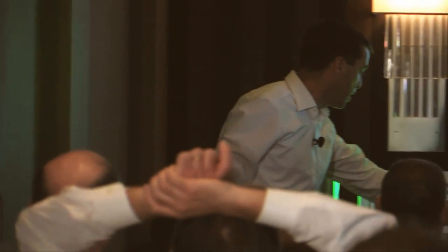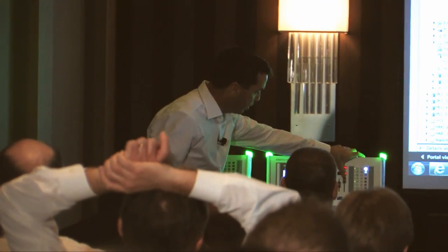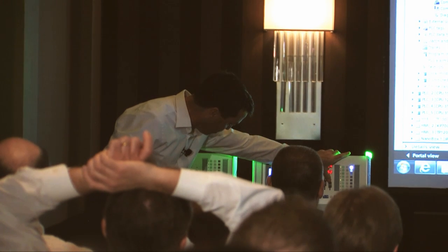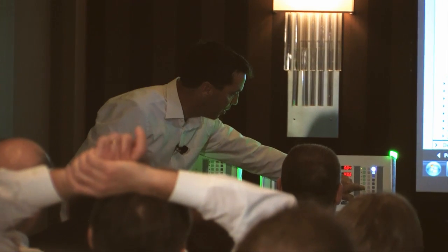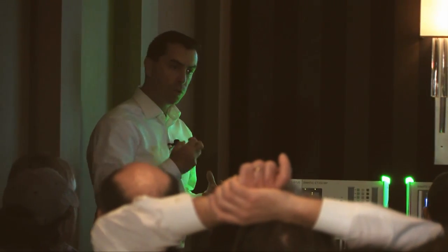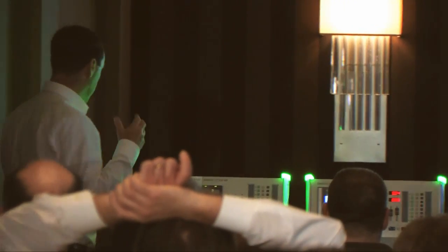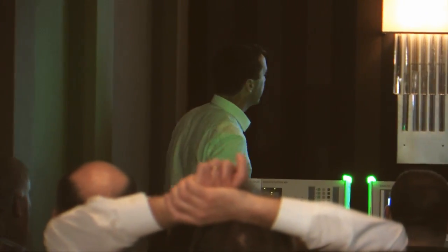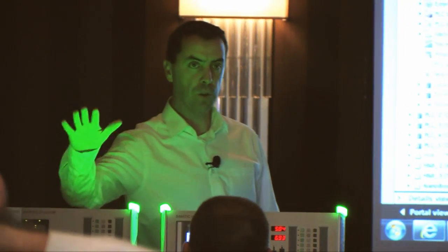So on the front of the kit then, I can jog it. I can change the different speed here. You can hear it speeding up, slowing down, stop, go the other way, speed up, slow down, and so on. A little later, I'm going to do this whole thing from scratch with an empty project. But I just wanted to show you here the real highlights: the easy way to use the technology object, which is the axis in your project. And you can have up to 20 axes that the 1500 can control.